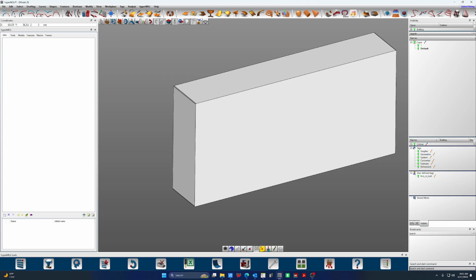The tools that they use to go from that 3D scan data to supplying us with a solid model usually means we have a ton of wild surfaces with vectors going all over the place. And sometimes, not always, but sometimes we can take a lot of those surfaces, and global fitting basically gives you a few different tools depending on if you want the surface to be very accurate to the parent surfaces, or if you want it to kind of soften the tangency between the surfaces.